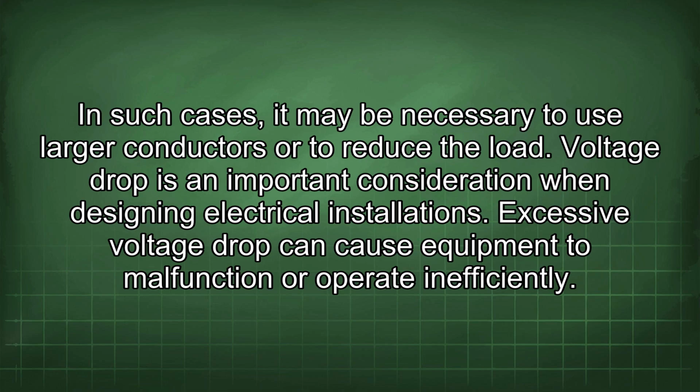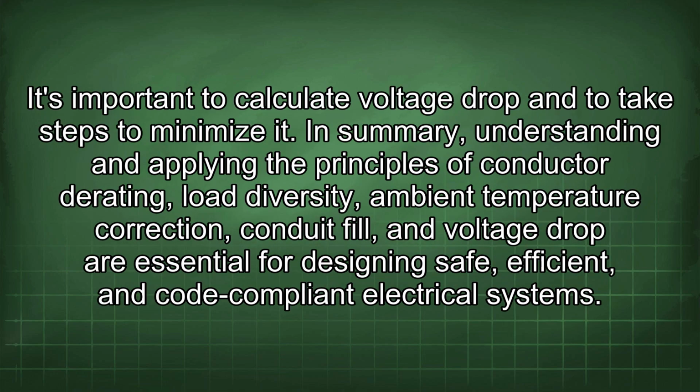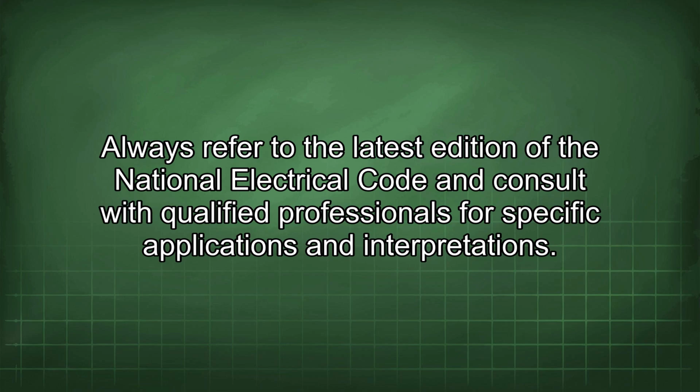Voltage drop is an important consideration when designing electrical installations. Excessive voltage drop can cause equipment to malfunction or operate inefficiently. It's important to calculate voltage drop and to take steps to minimize it. In summary, understanding and applying the principles of conductor derating, load diversity, ambient temperature correction, conduit fill, and voltage drop are essential for designing safe, efficient, and code-compliant electrical systems. Always refer to the latest edition of the National Electrical Code and consult with qualified professionals for specific applications and interpretations.